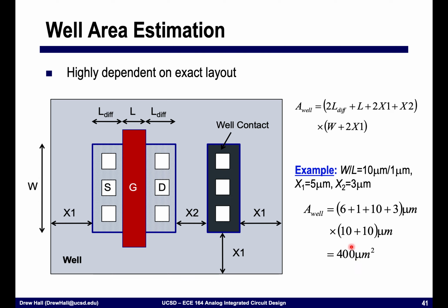And so this capacitance can actually be quite significant and can limit your performance. And so you have to think very carefully of whether or not it's worth dealing with the body effect and having the body tied to VDD, or if you really want to get rid of the body effect and tie this to the source, you're going to pay the price in terms of this capacitance.